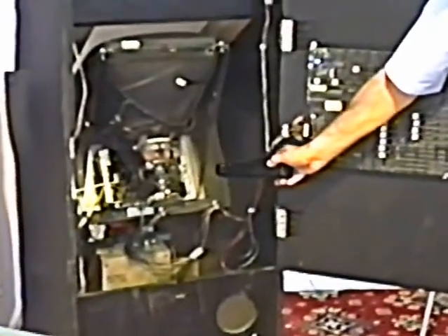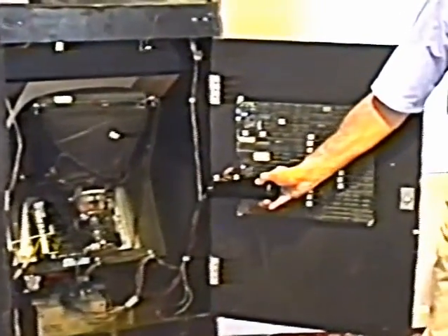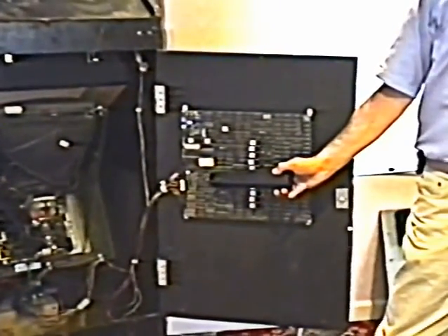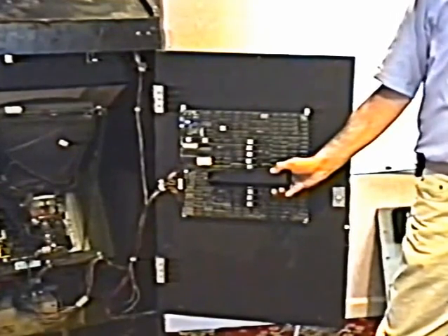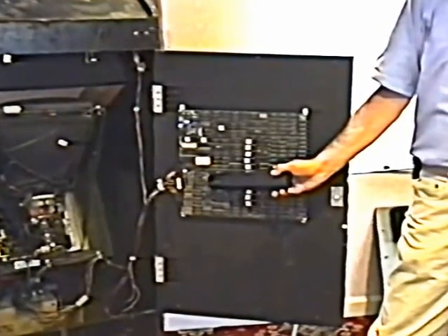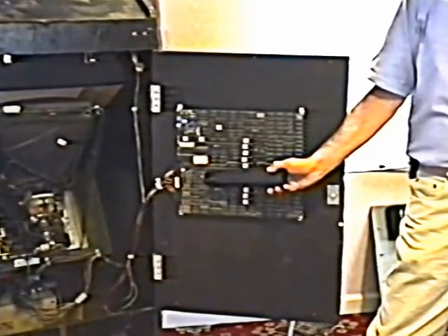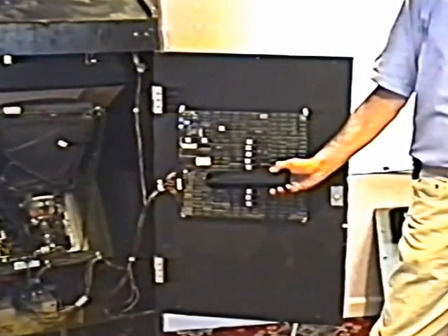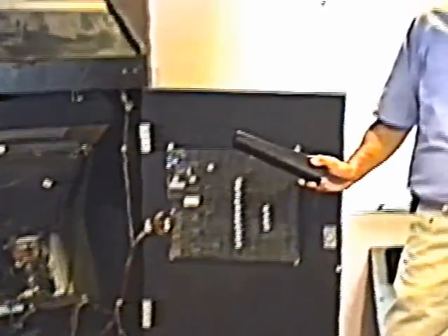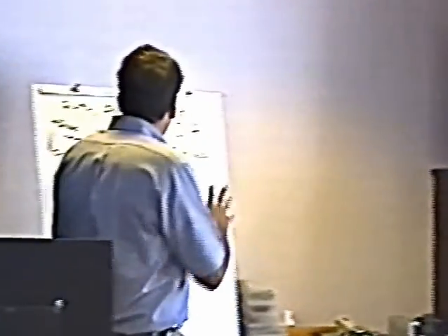By the time the current gets up here, through this wire, and over here to the logic board, maybe it's only 4.9 volts on the board. Sky Shark's a perfect example of it. This game doesn't even work well at 5 volts. 5.1, perfect. But I've had them at 4.95, and they freeze up, they shut down, all kinds of weird things happen. So I always set it to 5.1 volts on the board.